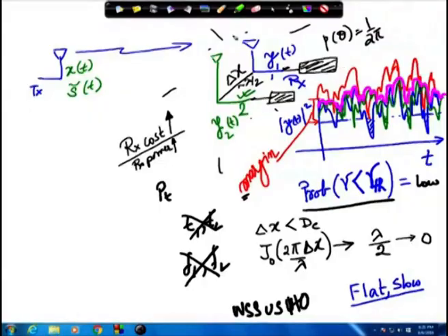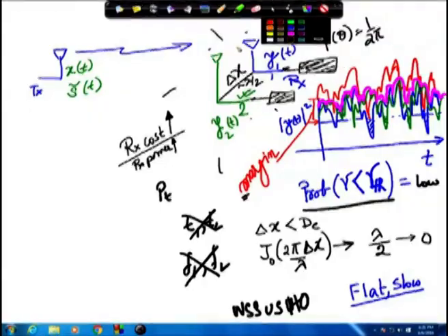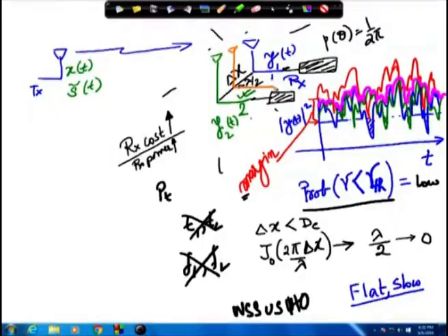Now, in the case that we place the antennas which are not separated by coherence distance, that means suppose we place an antenna which is somewhere in between and which is not less than the coherence distance. In that case, the signal will be correlated, but we have to find certain combiner techniques. There would be combining techniques at the receiver. So, we have to use a certain combiner technique, and still you could get something extra.